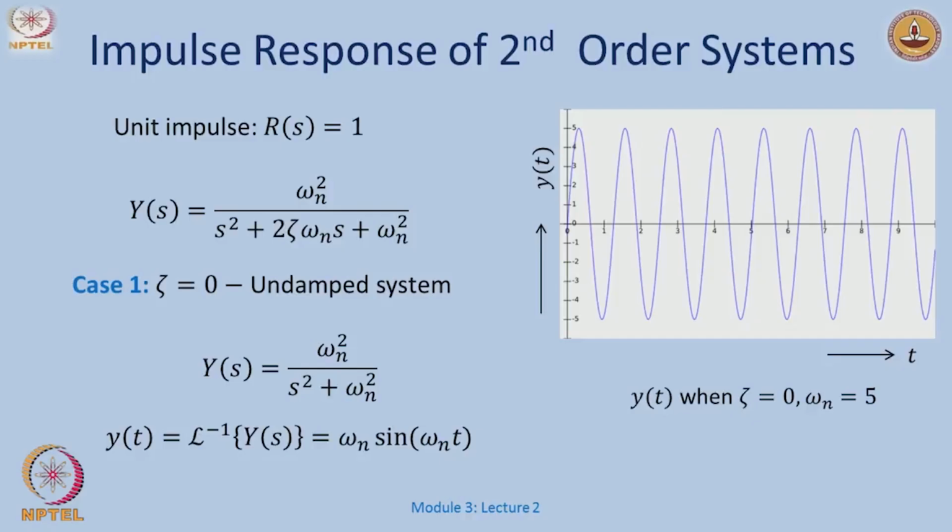So, here I have to be careful that there is another thing: not just a test signal, but something that depends also on the value of zeta, right. Earlier my formulas were very easy to remember, but here zeta adds more complexity, or rather, presents me with more test cases. So, Y(s) is omega n squared over s squared plus 2 zeta omega n s plus omega n squared.